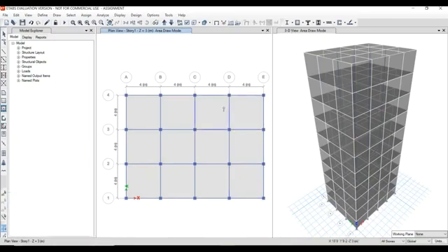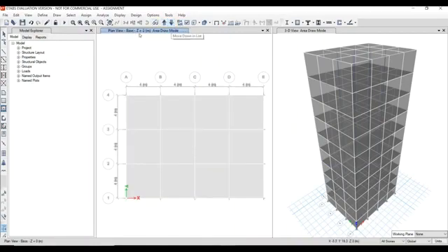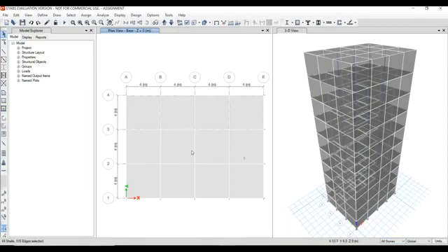And now we need to assign the loads. Before assigning the loads, we need to make sure that the base is a fixed base. To give the fixed base, go to base, plan view, z equals 0. In that place, we have the slab floors, which are already assigned due to the selection of all stories. Now select the individual stories. Delete this one, click escape, and now select every panel.